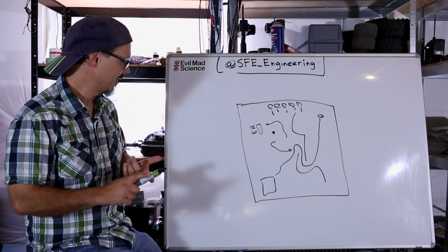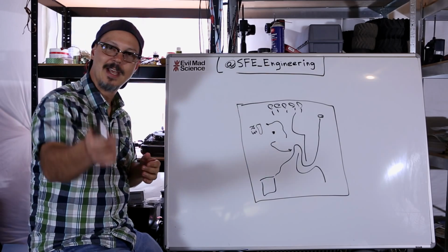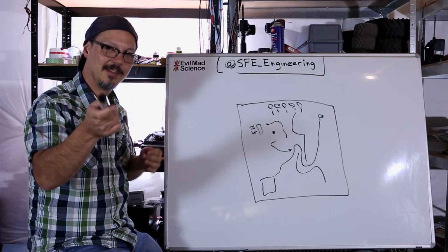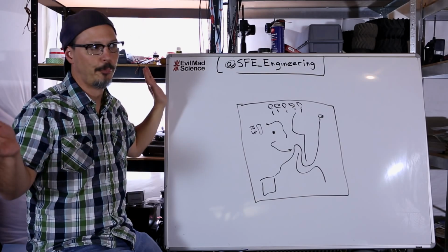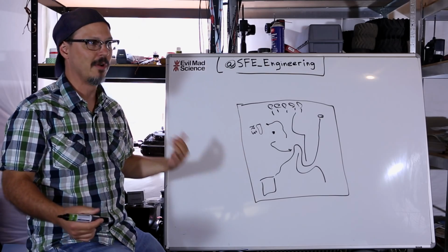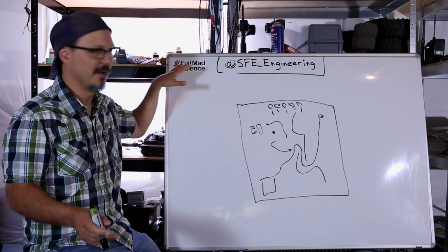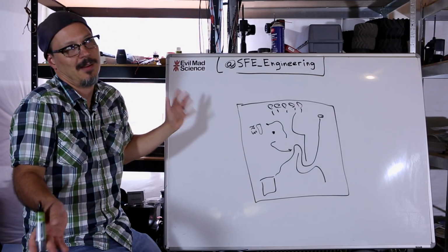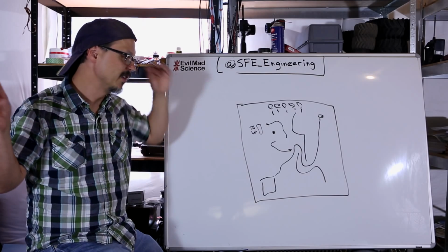So you run a prototype, you get it back and you build it, and then you test it. When you test, limit the current on your power supply down to 100 milliamps. When you build it, you're going to have a rough idea of how much current it's going to draw right off the bat. If you've got no input and no output, it's like 30, 40 milliamps when it's running quiescently.